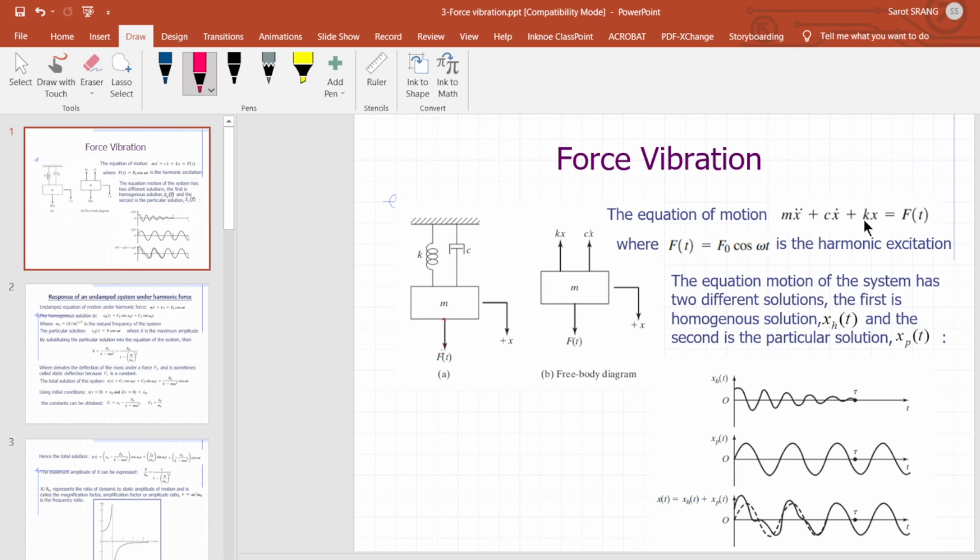And how can you find it? In that case, the right hand side is constant, then the particular solution is a constant, right? If the particular solution is constant, the derivative is 0, the second derivative is 0, which means k h equals f0, so the constant h must be equal to f0 over k. And actually we denote this as delta static, right? Static.